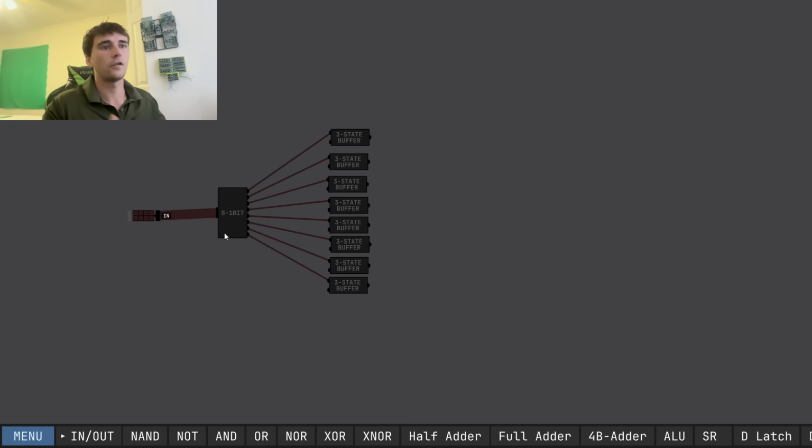So this right here just allows us to put this 8-bit thing back into 1, just to make life a little easier, because we are using an 8-bit opcode where the bottom 4 is for numbers, so we can store in the register, and the top 4 is for the control unit, so we know what to control.